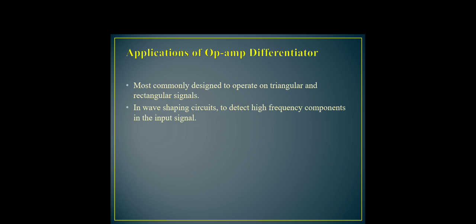Applications of op-amp as differentiator. Commonly, this circuit is used in wave shaping circuits to detect high frequency components in the input signal and to operate on triangular and rectangular signals.